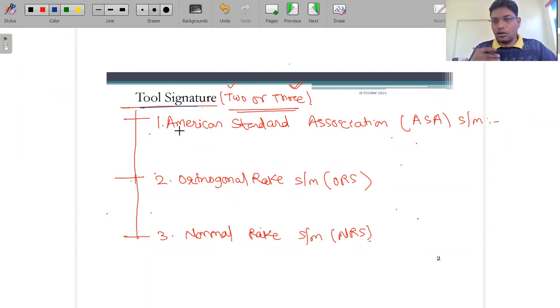The worker is the one machining these things, the engineer will not go there. The worker knows only what angle to create in the language you give them, as I created this model. Similarly, you will keep in mind how much the side cutting edge angle, how much the side clearance angle, and how much the back rake angle we have to create.